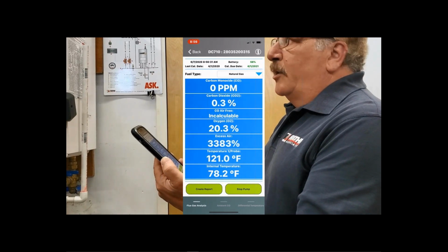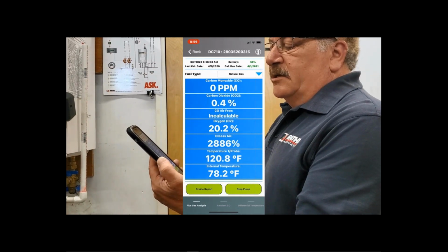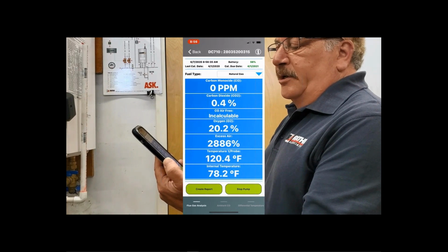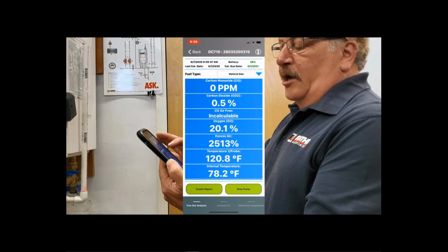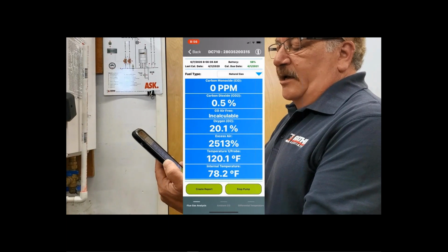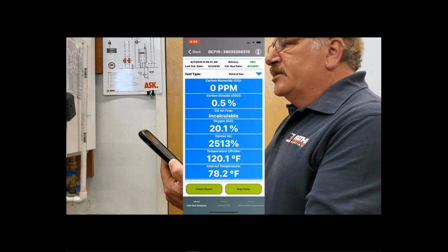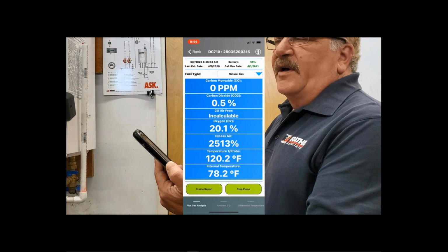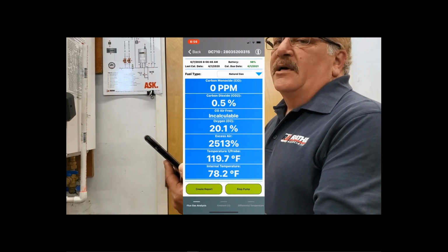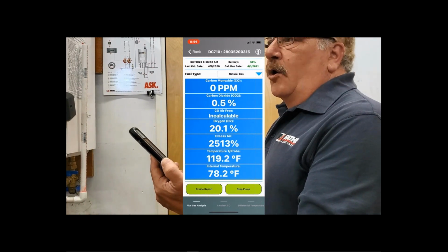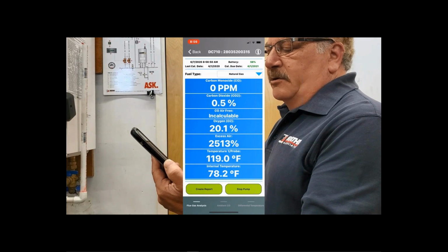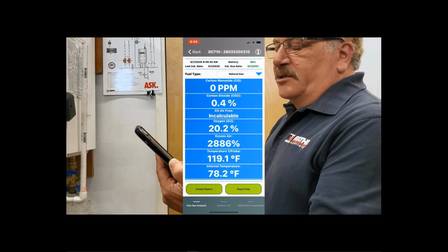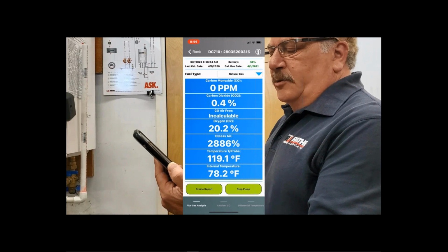So at the very top, while we're waiting for that, it says carbon monoxide, 0 parts per million. Underneath that, as you're seeing the rise, is carbon dioxide. CO air-free, this is an air-free CO device, so we can take carbon monoxide readings in an open environment, and that's what's known as air-free. That you'll be seeing coming up. Please be patient with the analyzers.